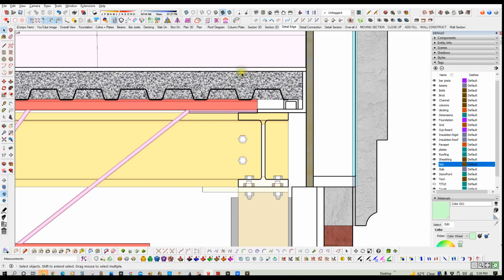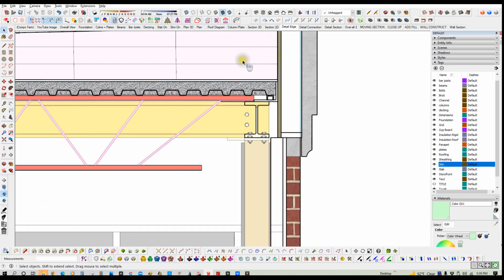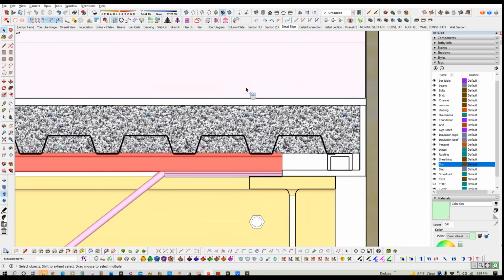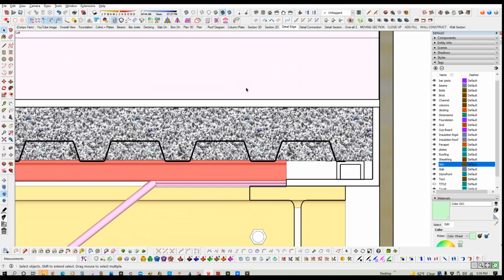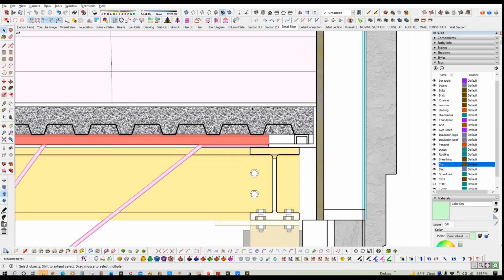I just put a space in here because in SketchUp lines will transfer through other elements sometimes. So sometimes it's best to just leave a little space so they don't sneak up through there. You see, I'm sure you've seen it where you put sheathing on a roof and the rafters all show. The best way to fix that is to leave a little bit of space. Real drawings and in reality, what we do is they're not necessarily to scale either. They're visual aids, if you will.